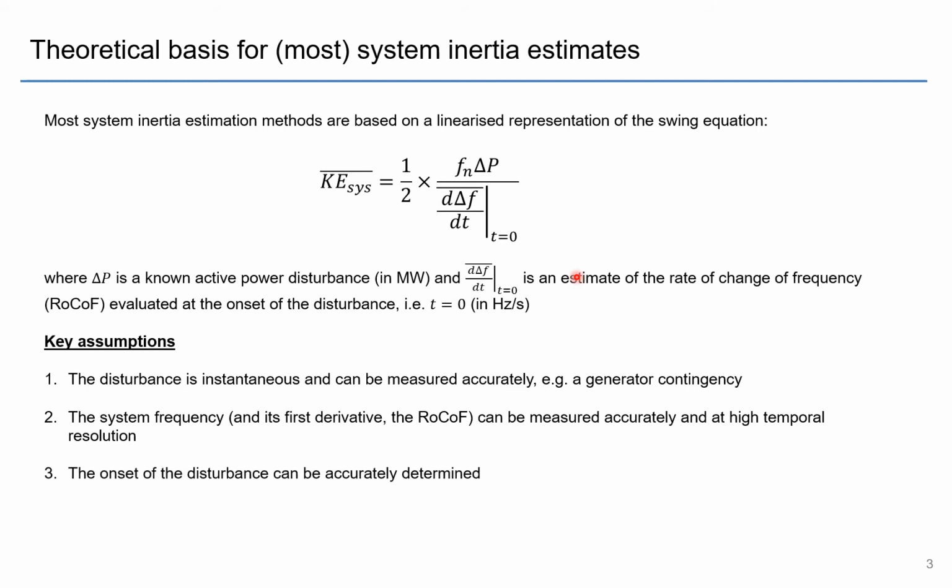Thirdly, the onset of the disturbance has to be accurately determined, because you're actually evaluating the RoCoF at the onset of the disturbance, so you need to know when that is. And that's not as easy as it sounds, and we'll go into some of the issues around that.